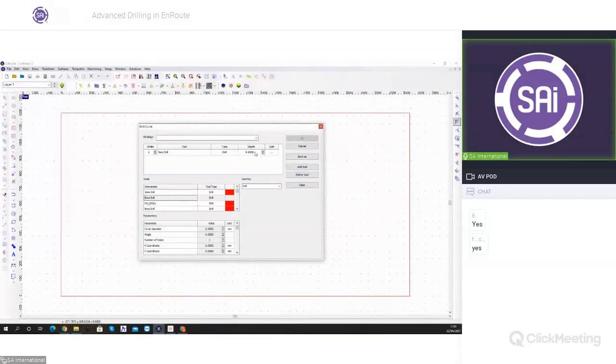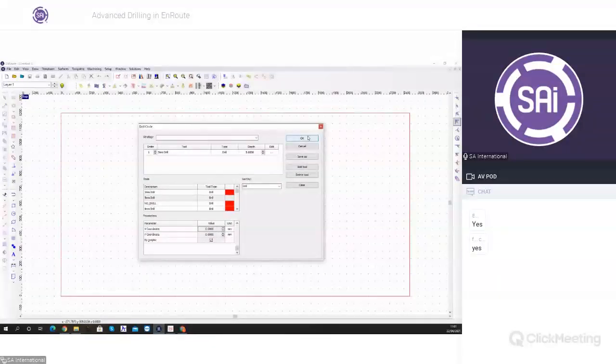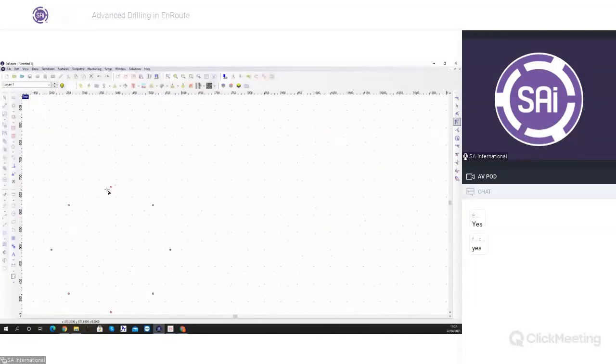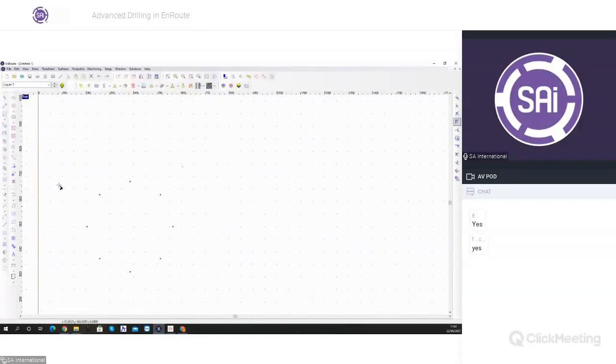What you do is you can select your drill here, you set your depth, you can define a diameter for the circle you want to put your drills along. Here you can choose your angle, which will define how the drills will be positioned on the circle. Just leave it at 0 for now. We'll choose 8. You can choose the coordinate of the center of the circle, or you can just define it by graphic. And then you can click on your plate, and as you can see, it will now have put the drill points that I've defined in the strategy.